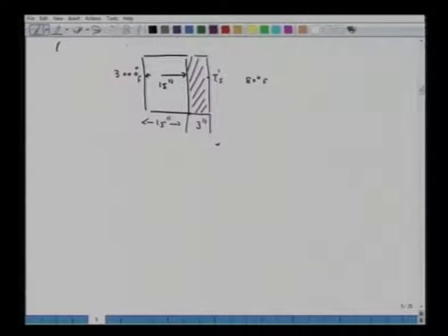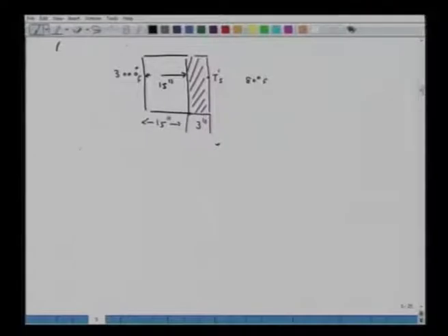Now, this is a multi-layered lining problem. So, you have to again apply that multi-layered lining formula, again equate conduction equal to convection plus radiation. I am omitting that step and I would like you to do that step, iterate it and get the surface temperature T dash S, which will come out to be 372 degree Fahrenheit.